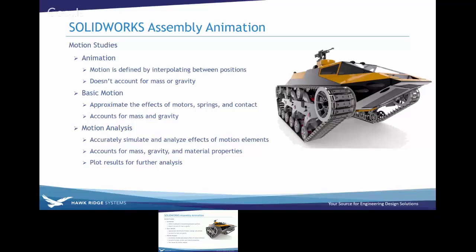So if you don't really care about the complete physical effects and you're not interested in reaction forces or graphing anything, getting any kind of result plots out of it, then basic motion is a good option. But if you do need those more analysis-level tools, then motion analysis is what you would need to use.